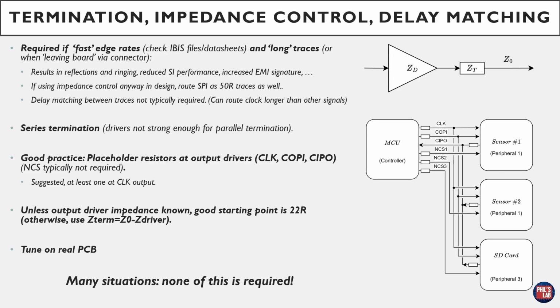Oftentimes it's recommended that you route the clock signal longer than other signals, but generally none of this is required. But keep in mind always to calculate your timing margins if possible, but oftentimes in SPI cases you can definitely get away with it.